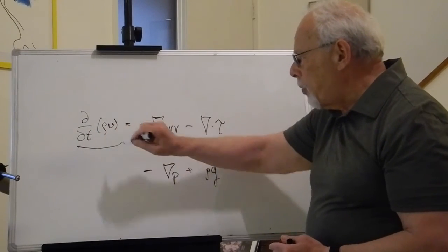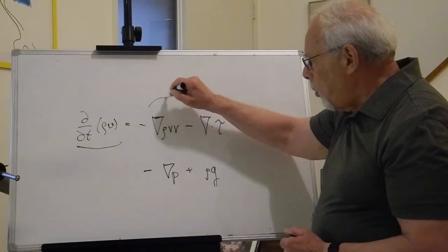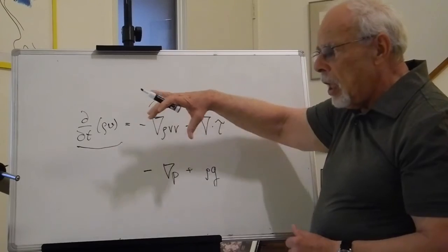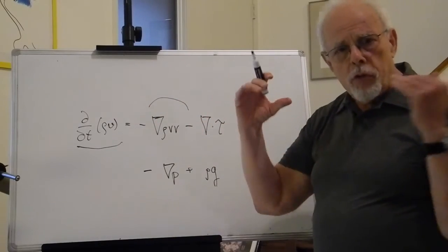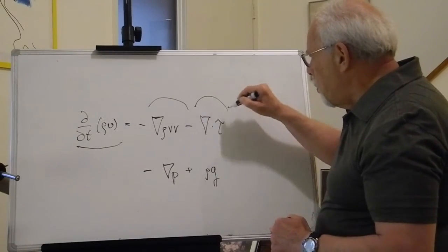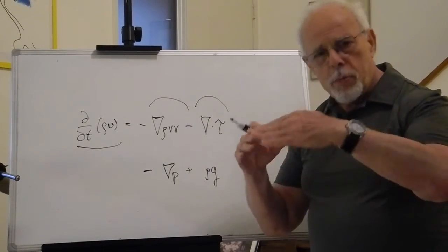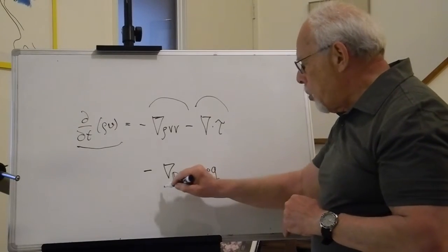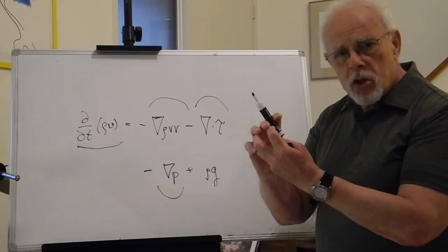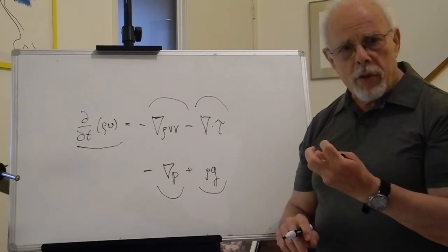That's the rate of accumulation of total momentum, that is the total impact of convection, of bulk flow of fluid, that's the total impact of the viscosity, of the cross migration of momentum, that is the impact of surface forces in all directions, and that is the impact of gravity.